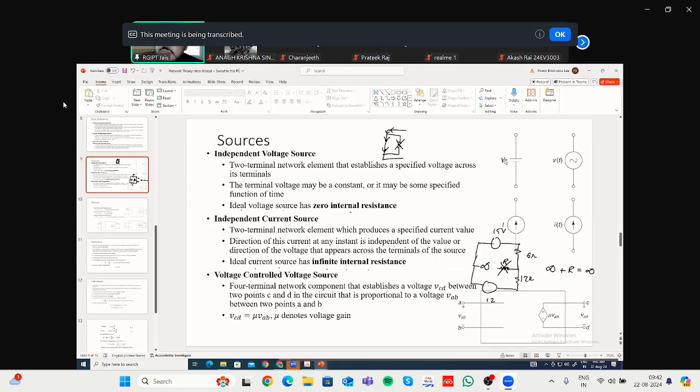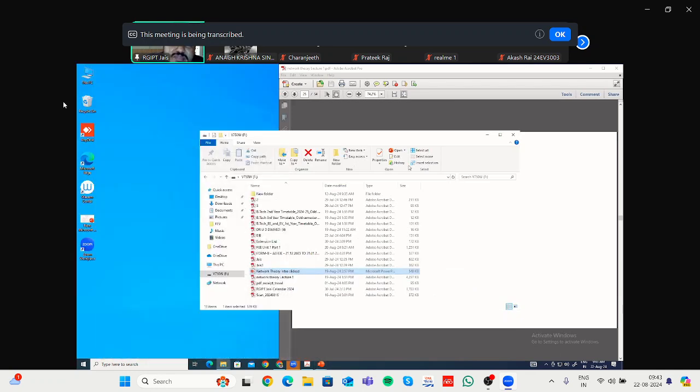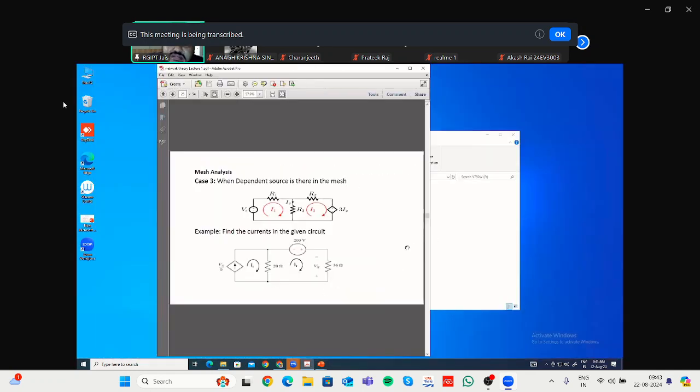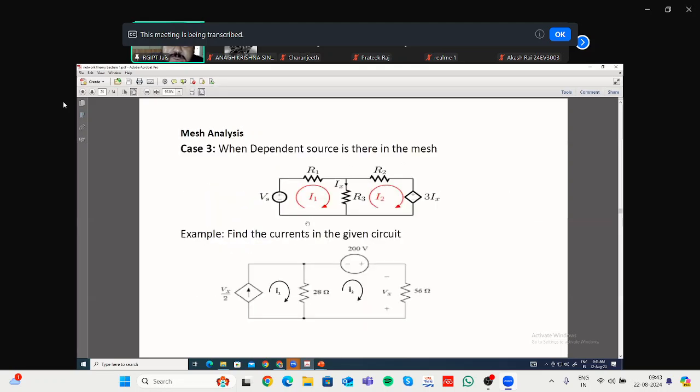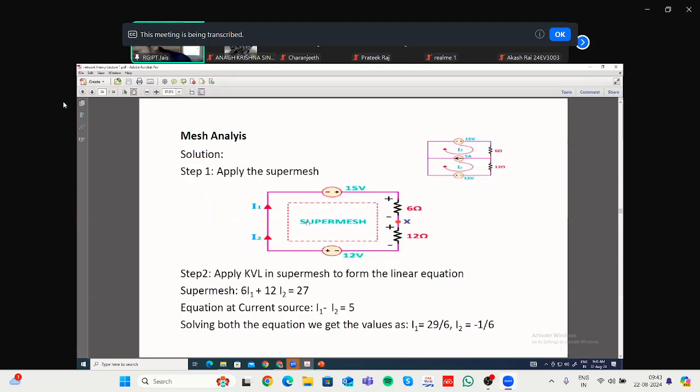Okay. Now, the next, Rajbir is saying it can be taken as I2 minus I1 if we consider I2 is greater than I1 for the super mesh. In super mesh, how can we consider it? Let me see. In super mesh, by just seeing this current, its direction and its magnitude, you can say that the direction is in the same direction as I1.